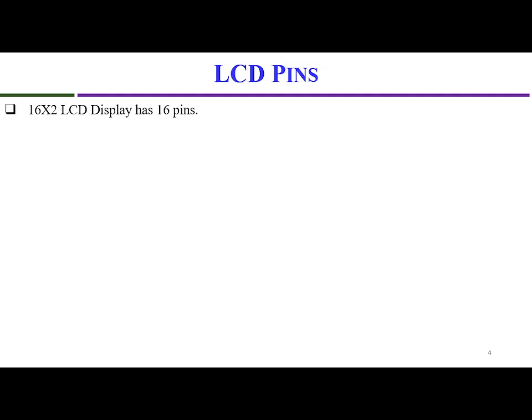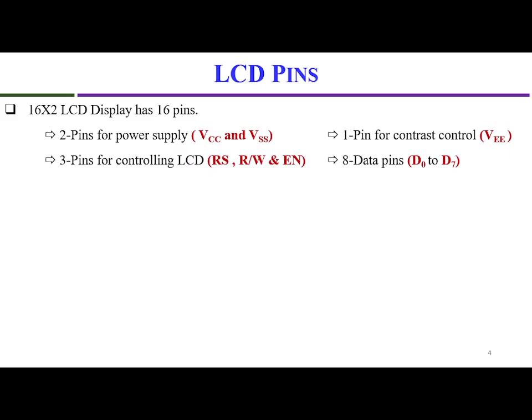Now we'll see the LCD pins. The display has a total of 16 pins, out of which 2 pins are for power supply, they are VCC and VSS.